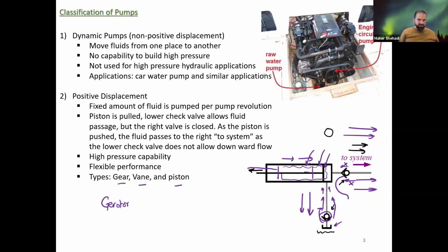And we'll check what the gerotor is if you're not familiar with it. In fluid power, MET 230, we actually did the gerotor motor, if you recall. We did that and the piston. The motor is essentially the same as a pump, except it receives fluid and delivers power through the shaft. With a pump, you deliver mechanical power and we convert it into hydraulic power, whereas motors take hydraulic power, pressure and flow, and provide mechanical power out. So we have the gerotor and then the vane.